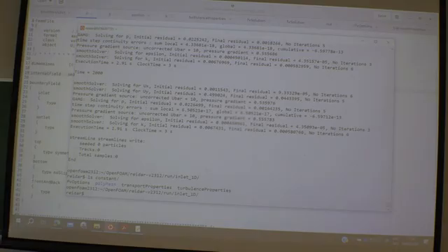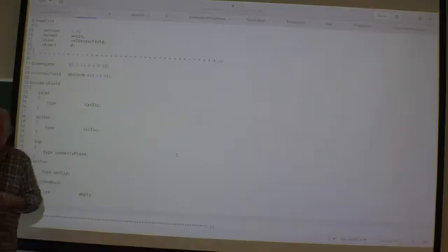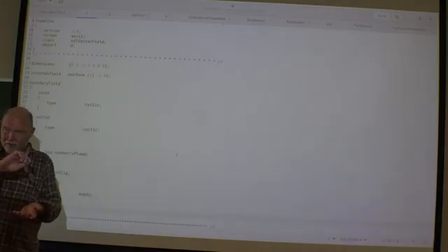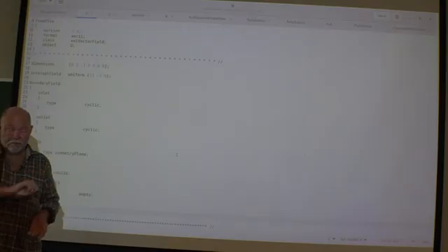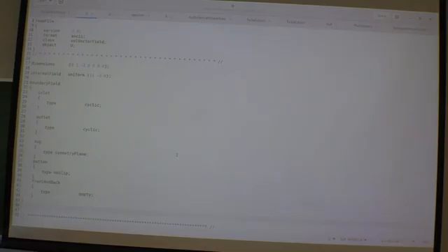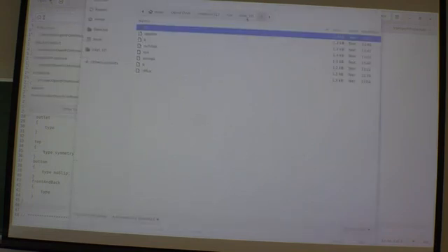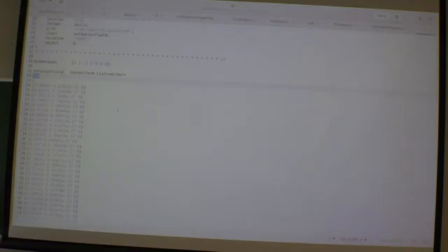Okay, say now that we accept the solution. Then, next step. If you use the exact same mesh as you have in your inlet, we are going to use this inlet, then this should be the same order. Then you don't have to look into the C files and the CY files. Then that's not a problem. But then what you have to do here is go to your solution and then say, for instance, now the velocity profile. Here I now have 100 internal points.